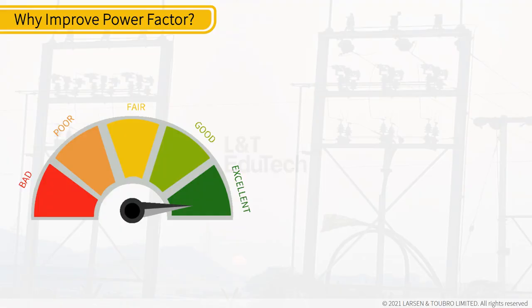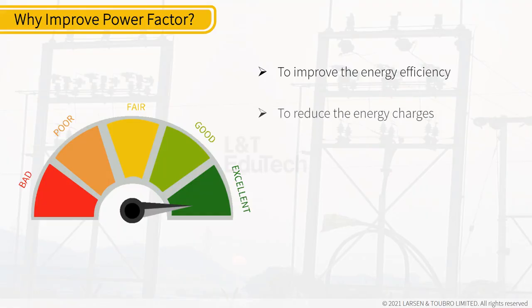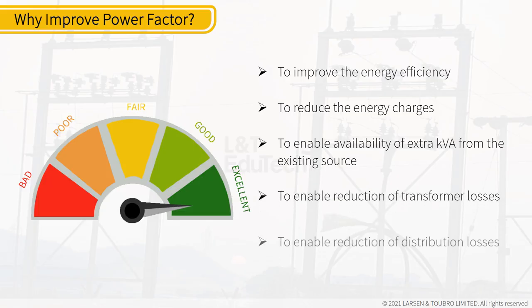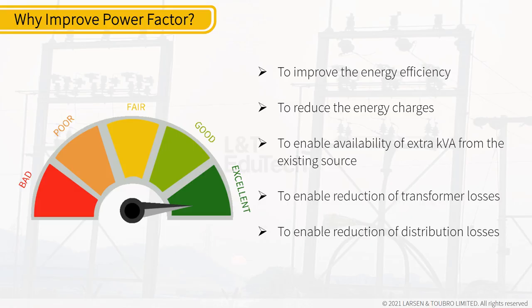The power factor needs to be improved for the following reasons: to improve the energy efficiency, to reduce the energy charges, to enable availability of extra kVA from the existing source, to enable reduction of transformer losses, to enable reduction of distribution losses, and extended equipment life.